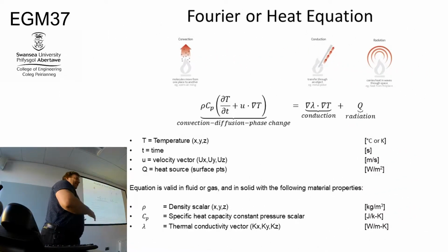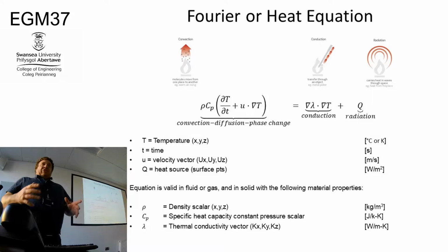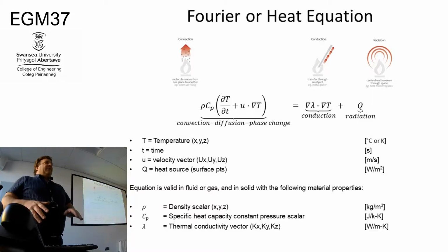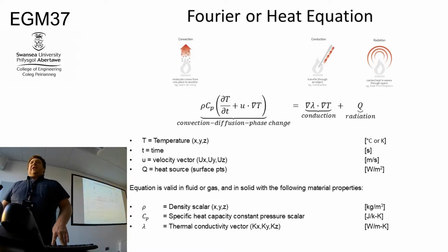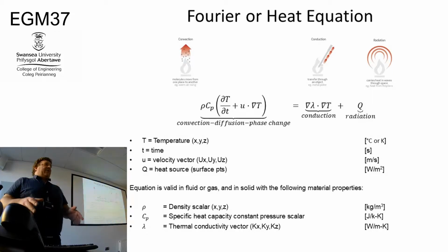Okay, so that was reality. Now I'm going to take you a step back to look at the maths. It's one of the things we're trying to do at Swansea, but it is possible to detach the fluid dynamics and the heat transfer. Because the heat sources are quite powerful, this is dominated by the heat transfer, but the fluid dynamics is in there. So what we've got is the Fourier heat equation. The left-hand side carries the convection-diffusion terms, and then you've got your conduction terms and your radiative heat source terms on the right-hand side. That just defines the transport of heat within or underneath the zone of the laser.